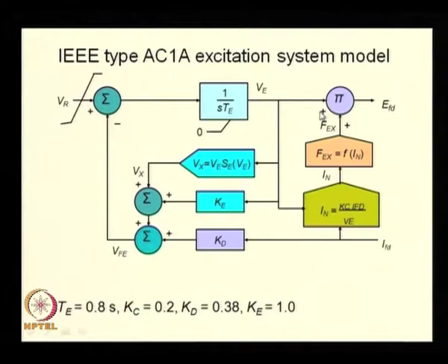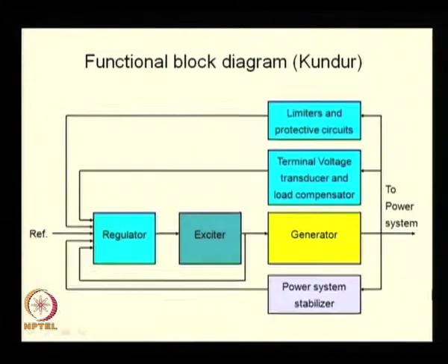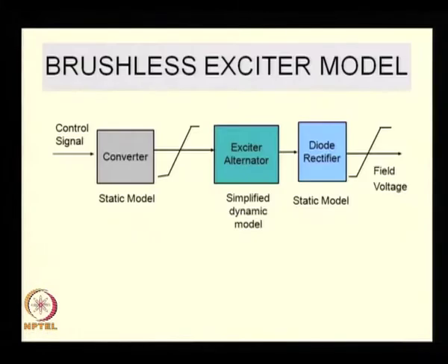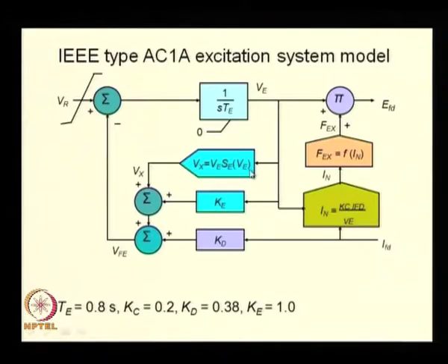Okay. So, these are what are known as typical block diagrammatic components which are used in trying to model an excitation system. Of course, this block diagram here which uses Laplace variable s, in fact 1 upon s, is essentially an integrator, an integration function. So, this 1 upon s here represents an integration function. Now, this of course was a model of the power apparatus. Okay. So, what we did was roughly model the excitation alternator by a differential equation and then converted it into a block diagrammatic representation of this kind.